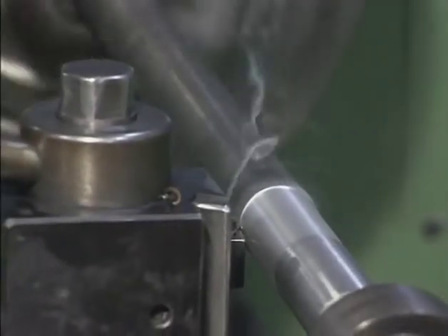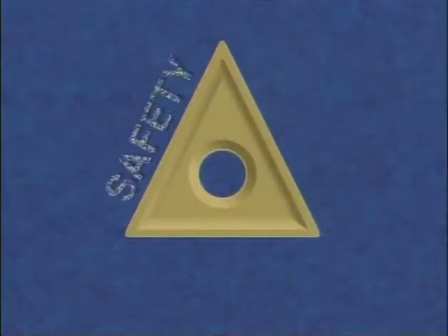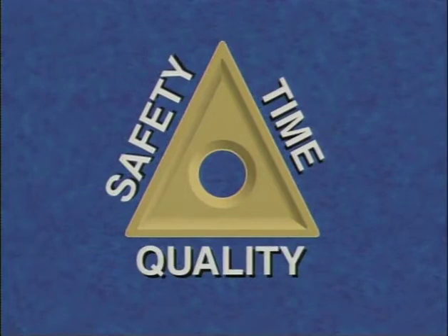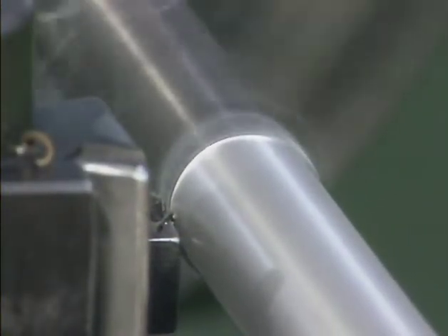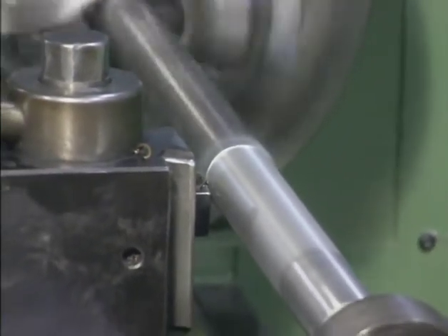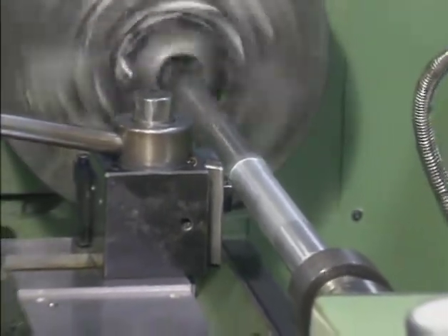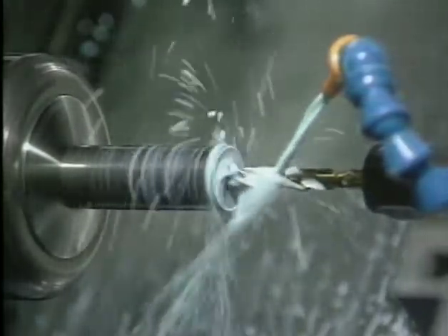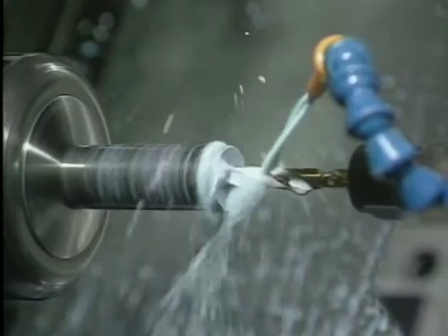The main objective in the selection and application of cutting tools is to safely machine a workpiece in the shortest possible time while meeting the part's quality requirements. Furthermore, the specified tooling should be the least costly and least complex tooling available to satisfactorily fulfill the qualitative and quantitative workpiece demands. It is estimated that nearly 50% of all cutting tools are used incorrectly. Additionally, the number one error when formulating tooling selections is calculating monetary savings based on lowest cost per tool rather than on maximized productivity and extended tool life.